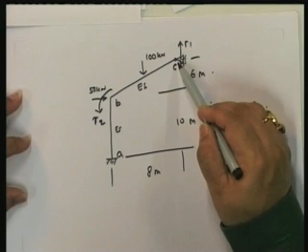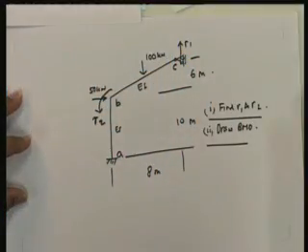Okay? So therefore, one aspect that I would like you to look at when you're doing this assignment is not just get the numbers, but once you get the numbers, you also try to see what effect, because I've got exactly the same member with exactly the same load, and since I have the same member and the same load, the only difference here is this support condition. So this difference between the two answers is going to give you the effect of changing this fixed to hinge, and that is something that I am going to concentrate on the next time.